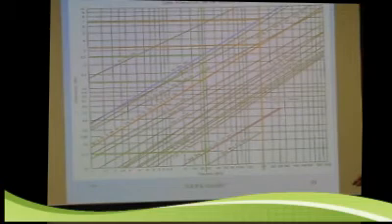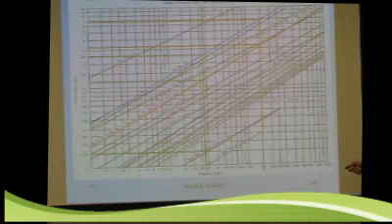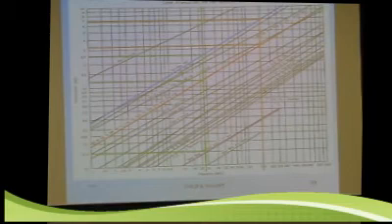Now, if you look down here at 4 megahertz, which is 80 meters, then you're only losing 0.6 dB with RG-8. I see RG-58 is about 0.7. So it's much easier to use coax, or you pay much less of a penalty of loss with coax, at lower frequencies than at higher frequencies.